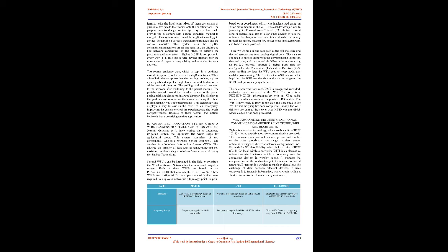Zigbee is a wireless technology, which holds a suite of IEEE 802.15.4 based specifications for communication protocols. This communication protocol is less expensive and similar to the other proprietary short-range wireless sensor networks. It supports different network configurations.